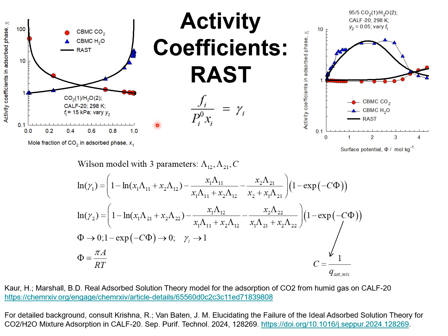In order to satisfy the limiting conditions discussed in the foregoing slide, we must use models to describe the activity coefficients that allow the proper limiting behaviors to be reflected for mixture adsorption in microporous crystalline materials such as metal organic frameworks and zeolites.